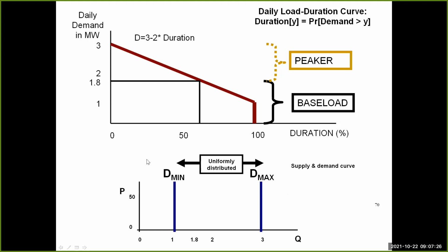Yeah, so every load during the day will have a load duration curve, but one load duration curve could actually summarize different kinds of load curves over the day. Why is that? Well, it's because we summarize some information here. So we actually lose a little bit of information. It's a summary. It's not perfect. Okay, now why might this be good?